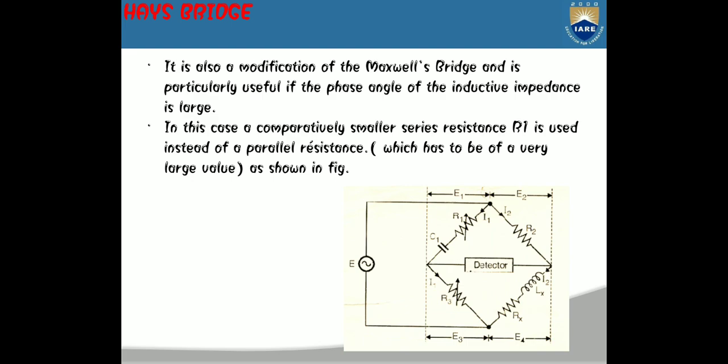Before those limits are approached, the ESR of the capacitor will likely have a significant effect and have to be explicitly modeled. For ferromagnetic core inductors, there are additional constraints. There is a minimum magnetization current required to magnetize the core of an inductor.